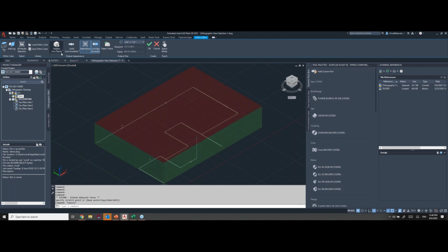And hidden line piping, I turned it on, so by default it is turned on. Even if you did it in your template and you don't want to show it on a specific drawing, you can control and make the changes on the fly here. So it's not that if you do it in the template, it's the end of all. Some feature enablement that you made in the template can be overridden while generating your orthographics.